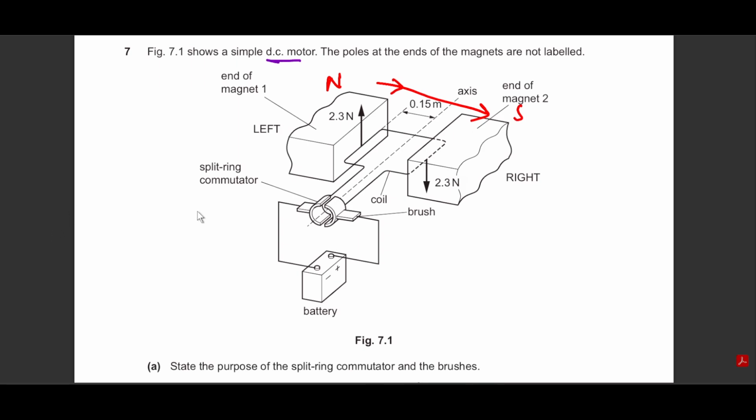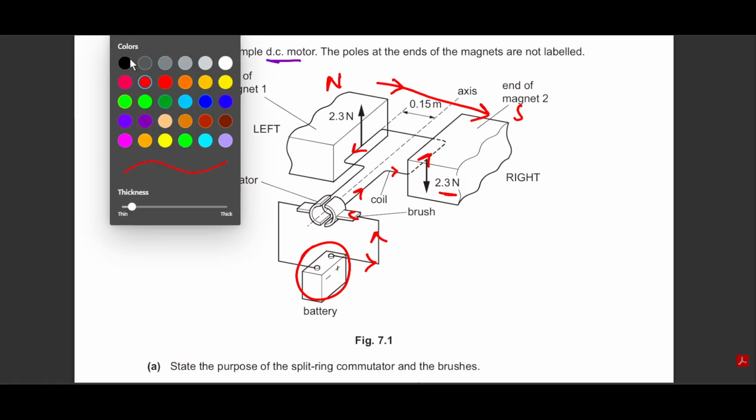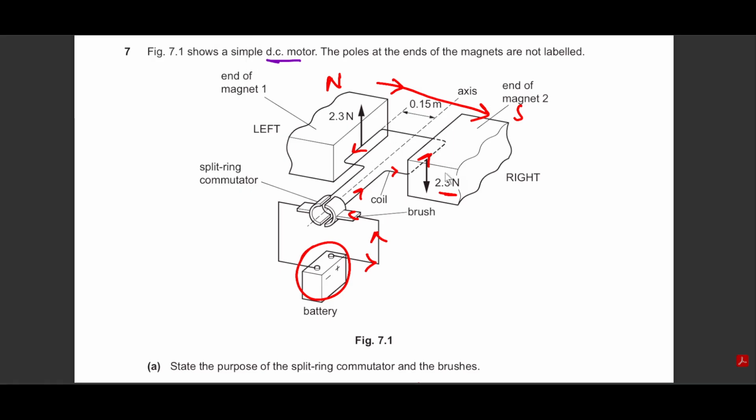You see, you need to use Fleming's left-hand rule, but there's some information that's missing. The force is given, we accept that, but the current is not given. For current, you need to look at the battery. The current moves from the positive terminal through the wire in this direction, completes a loop and comes back again in this direction. So it's your choice which reference point you want to develop. You can stand on the right side or on the left side. The answer will not change.